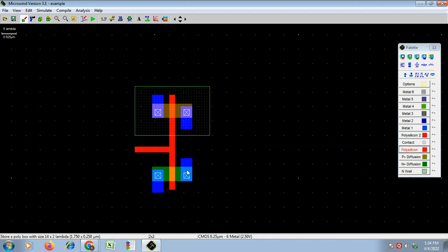So you can consider that terminal of PMOS and NMOS as a drain terminal. Okay, so first now we will connect this drain terminal over here. We have shorted this and we are taking output from here. Okay, now this is the drain of PMOS and NMOS, we have shorted and we have taken the output.